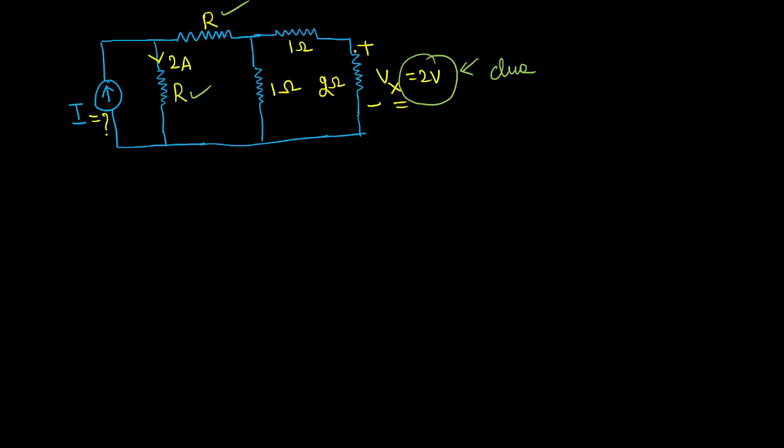Sir, see this. For this particular resistor, the value of the resistance is 2 ohm, and the voltage drop across the resistor is 2 volts. Now tell me whether the resistor is a passive element or an active element. Sir, we know resistor is a passive element. For a passive element, the current entering point must be plus, the leaving point must be minus. Now see there, they have already given the polarity.